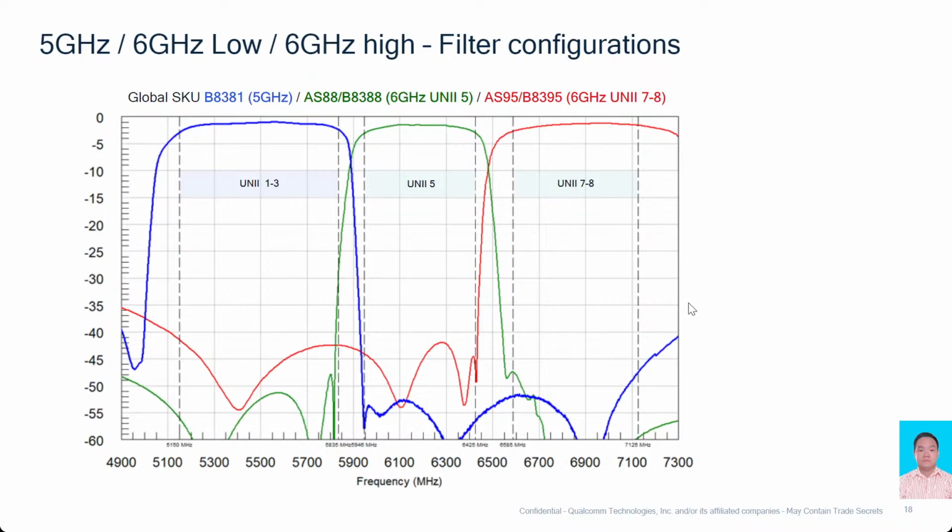We offer support, from board layout to the end of the system design and vice versa. Board layout for 5 and 6 gigahertz filters is very, very critical, very, very important. Different than what we've all been used to in the past, working with 2.4 gigahertz types of frequencies. Placements of vias and things like that are so important. And we offer, I don't want to call it a service, but we offer personal assistance there, free of charge.